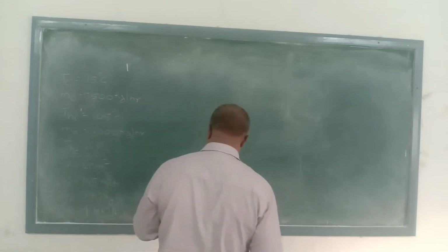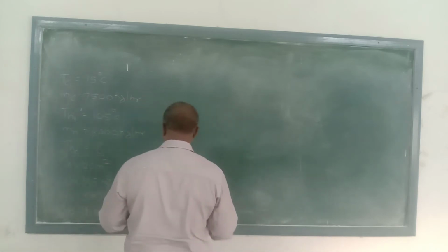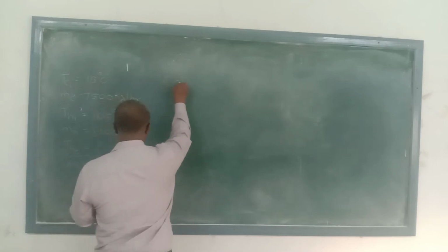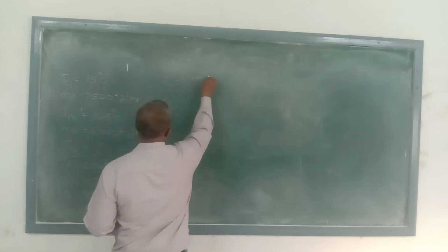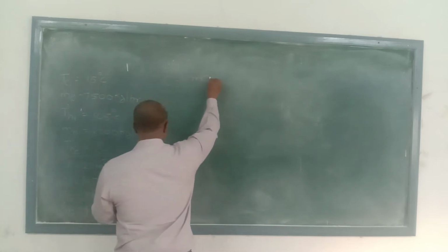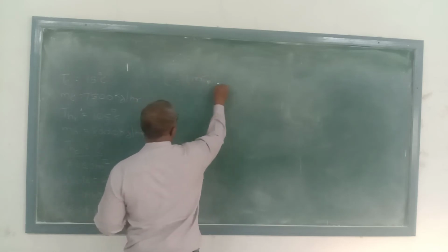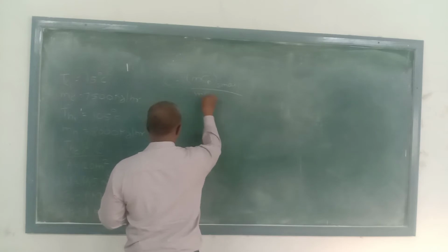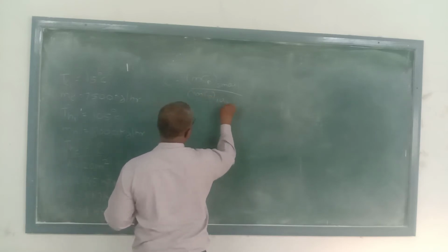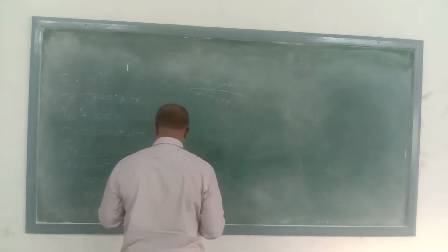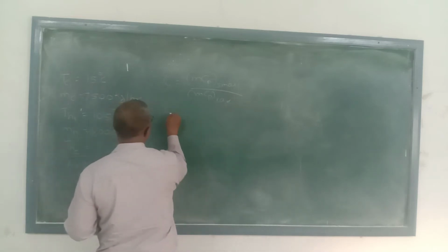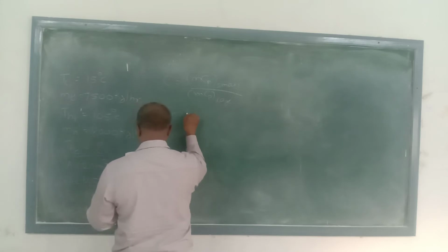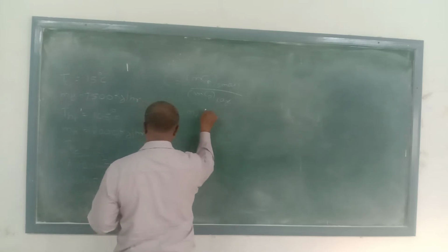So first of all we have to calculate the capacity ratio. C is equal to mCp small upon mCp large. So CH, we have seen this term in the derivation, mH into CpH.